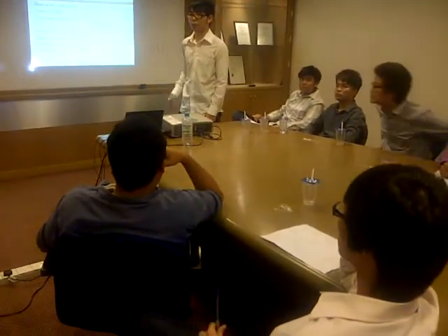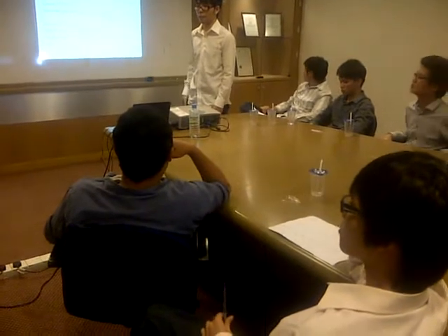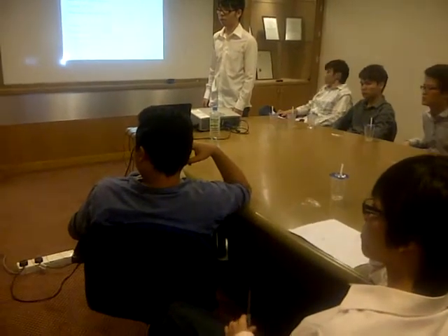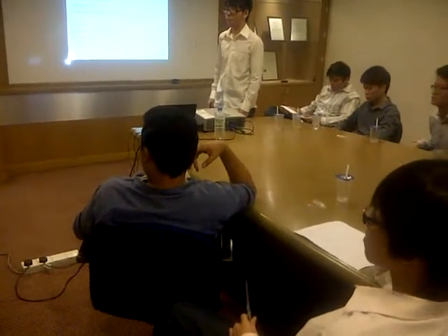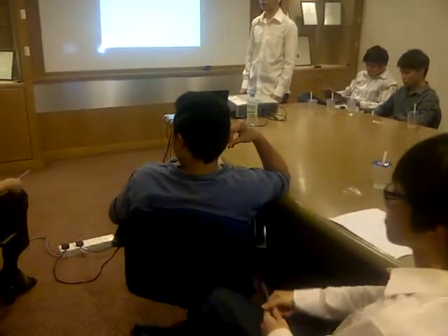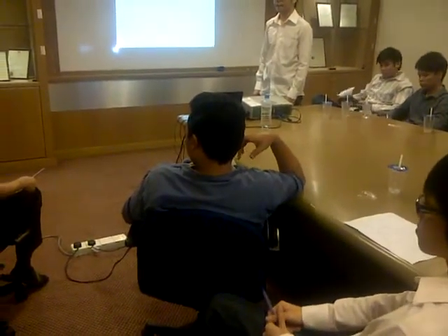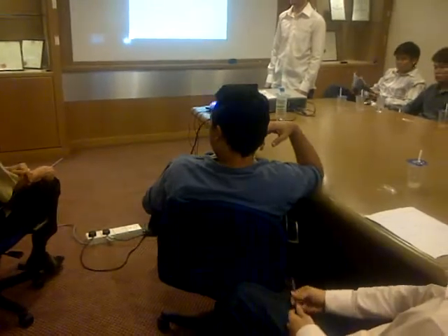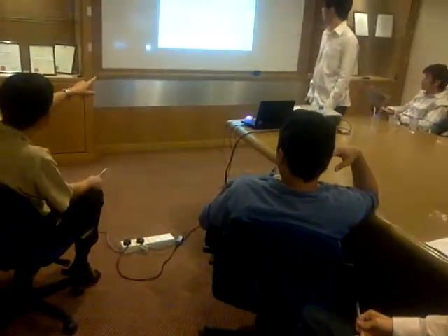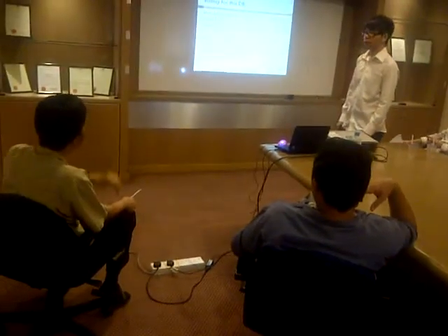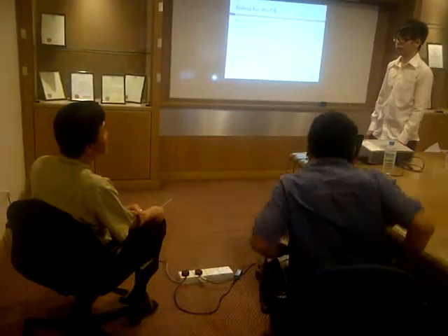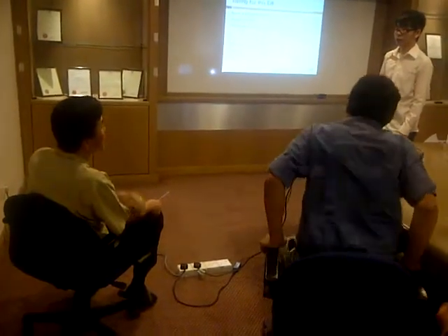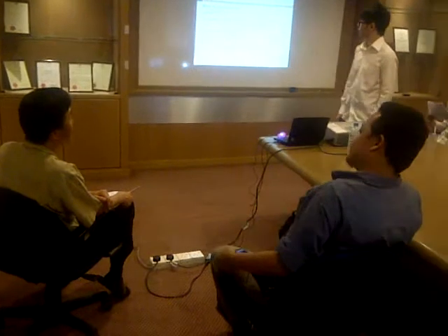The 60 is MCCB for each. Oh, 60 MCCB for each. Yeah. So you've got aircon, power, and lighting. Yeah, 3. Even 60 for 3, 60 times 3 is 180. Just the socket outlet by itself already takes 112. It's not logical. Imagine your biggest load is aircon, not power points.